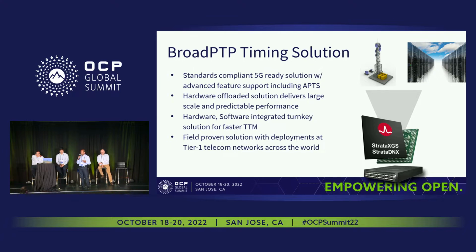Most of our silicon has embedded CPUs, and BroadPTP runs inside that silicon. That means it is essentially a hardware offloaded solution with dedicated CPU cycles and memory, so the customer can realize the performance that we tested in our lab. If you were to do it on a host CPU, the timing process would need to share resources with other processes, and the performance becomes unpredictable. That's a key advantage of BroadPTP.